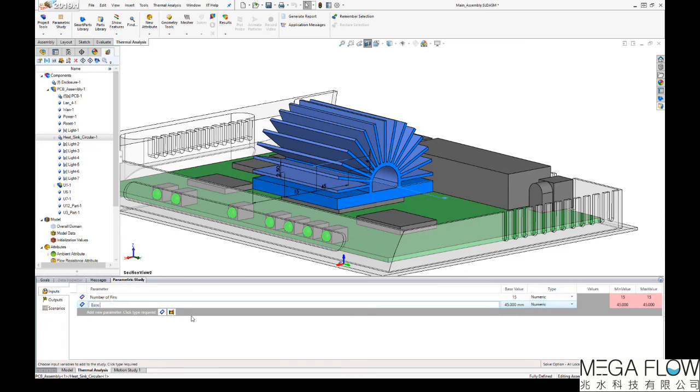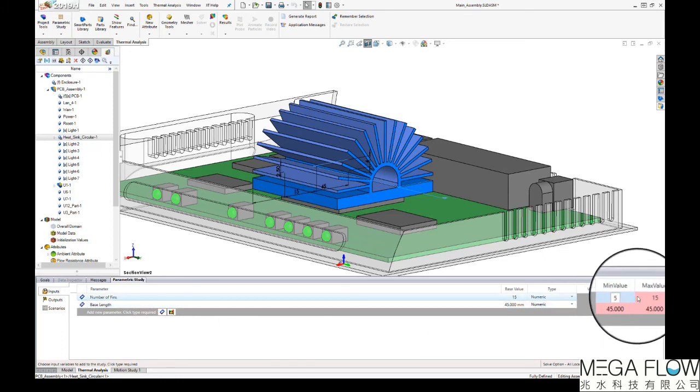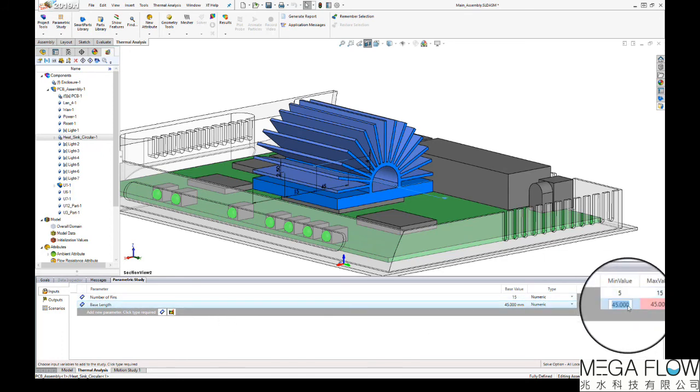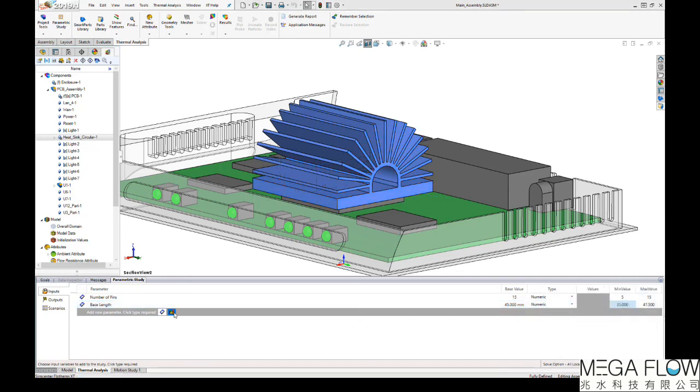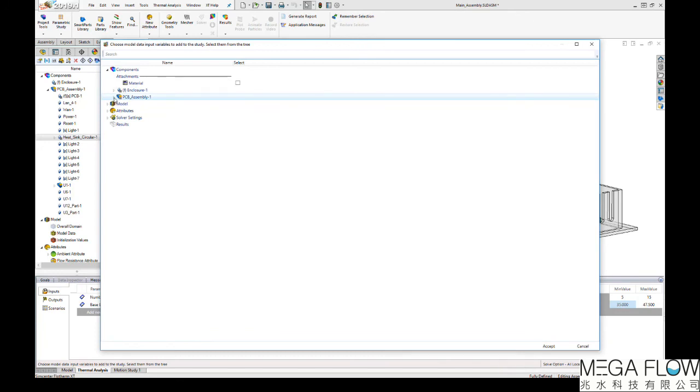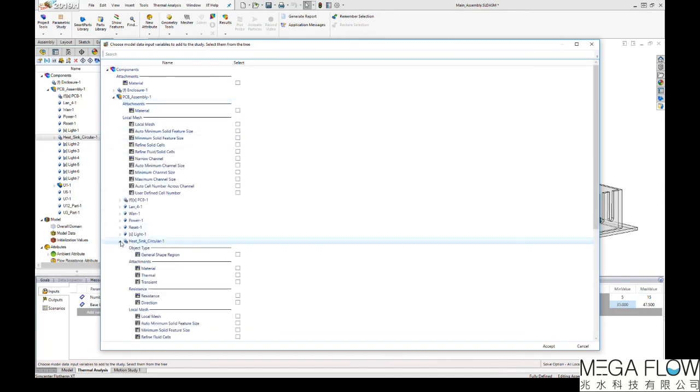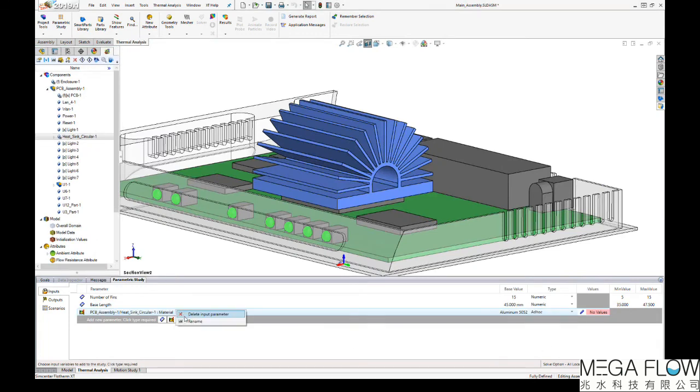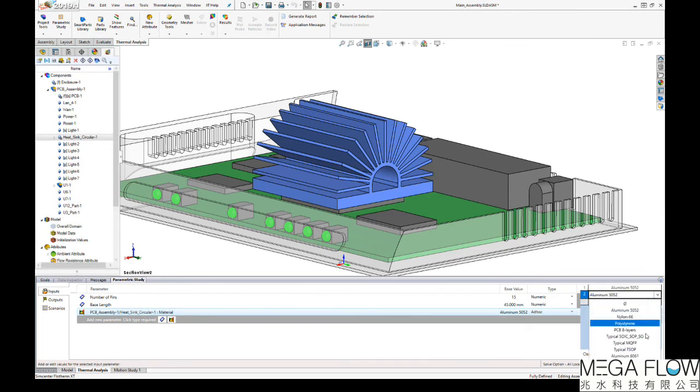Once the study has been activated, the user is able to set up the input and output variables for the study. For the input, you are not limited to numerical entries such as dimension, as a number of these external optimizers can accommodate input to say the material applied to a part. It is possible to define an ad hoc or linear step variation, as in a manual variation, or a range as in DOE. Usually the output variables are left as just recording the value.